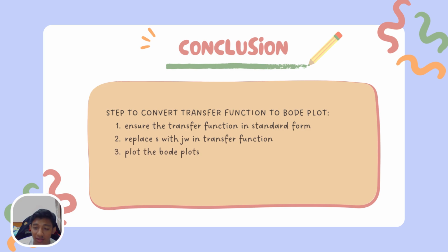And the second part is the steps to convert a transfer function to a Bode plot. First, ensure the transfer function is in standard form. Second, replace s with j omega in the transfer function. And third, plot the Bode plot.